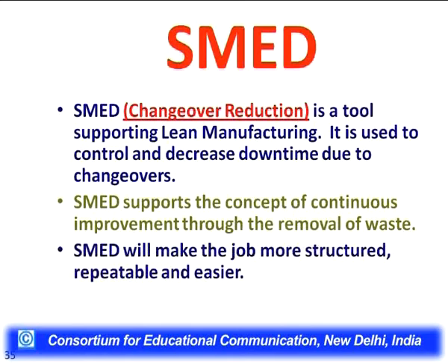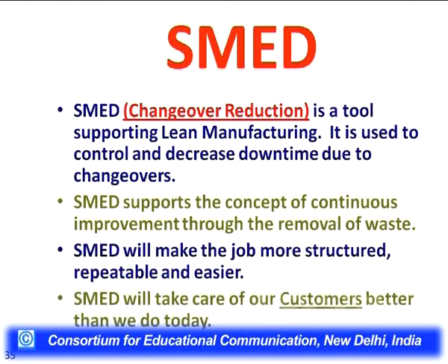SMED will make the job more structured, repeatable, and easier. Three things are being talked about here. Structured means streamlined. The process will be structured and streamlined so that it is repeatable. When these two things are there, then the process becomes easier to implement also. SMED will take care of our customers better than we do today, because the lead time is reduced. The customers will get the product faster, because we have implemented SMED where the setup time is drastically reduced. The customers are going to get the material very fast.